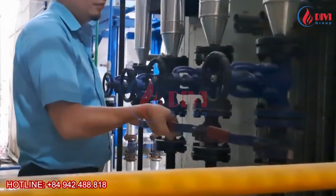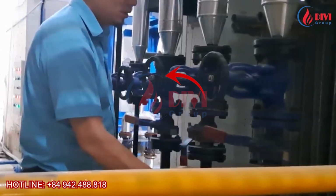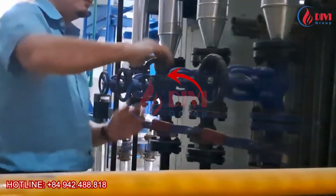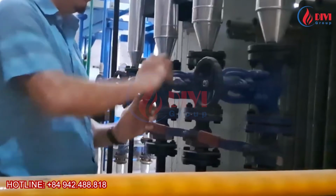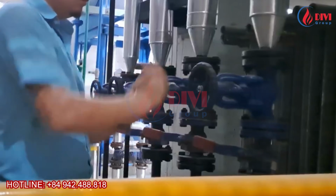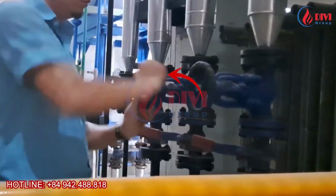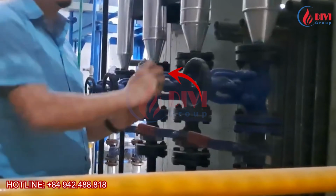Common mistake to avoid. After completing blowdown, it is mandatory to close the manual globe valve. Many operators skip this step, which leads to full pressure and sludge acting on the ball valve, causing rapid leakage and damage to the ball valve. Important: the blowdown procedure is only considered complete once the globe valve is properly closed.